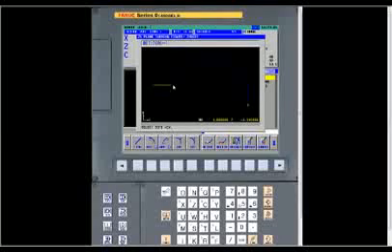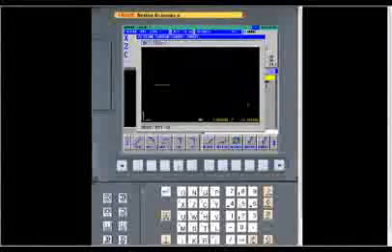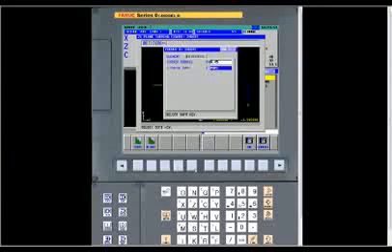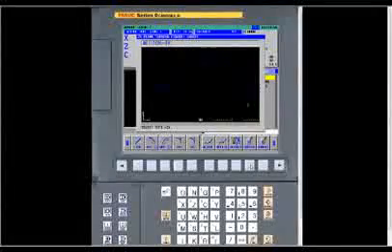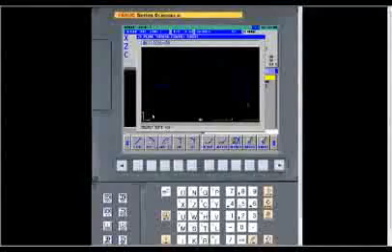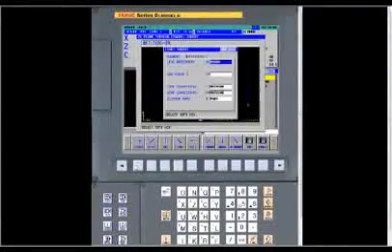And so now here we're to this shoulder. And now at this point, I know in this corner there's also a radius. It's a 450 thousandths radius. Enter that. Then say OK. Now the reason it didn't draw it yet is because we haven't told it which way to go yet. So we're going to do a line.